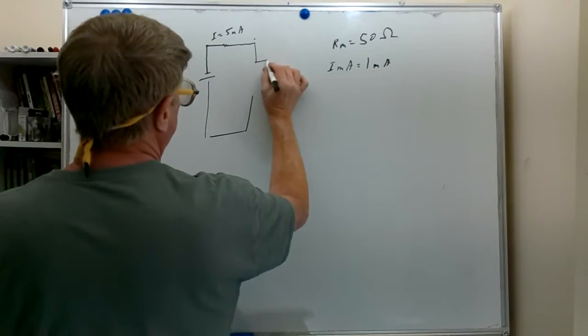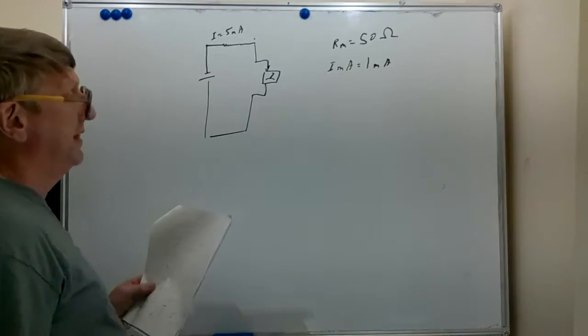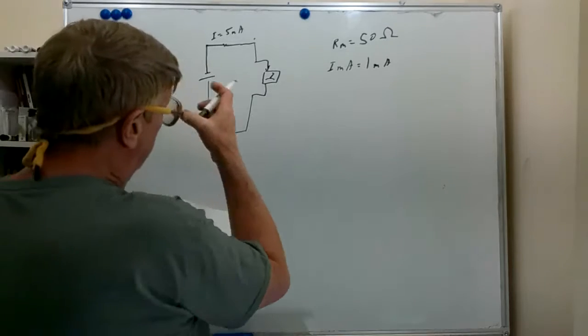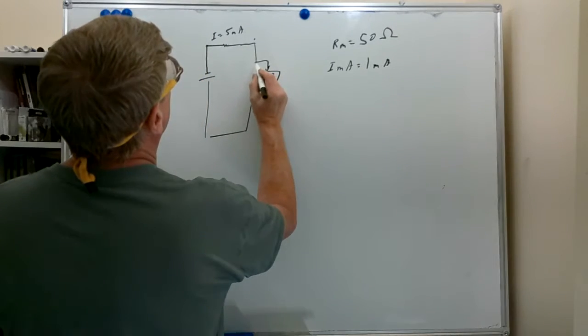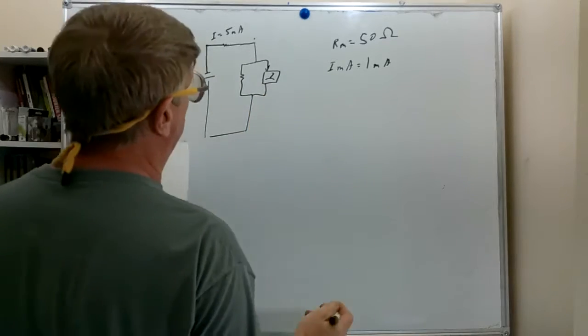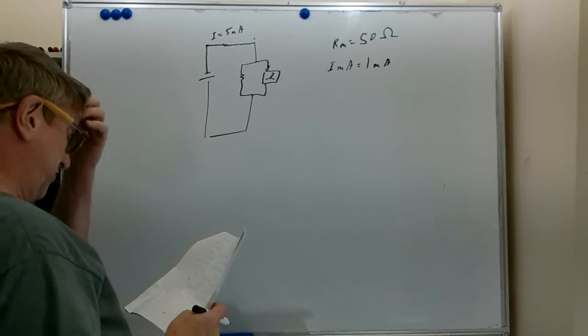So we connect our current here. Well, we're 5 milliamps. It's a 1 milliamp meter, so we're going to slam that needle all the way to the right against the peg. So what we do, we add what's called a shunt resistor. Resistor in parallel or in shunt with the meter. So some of the current goes to the meter and some of the current goes through the resistor.